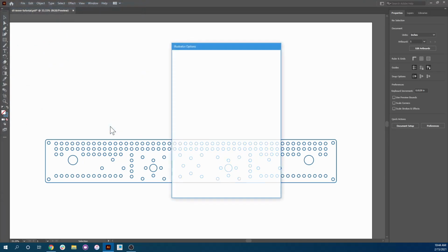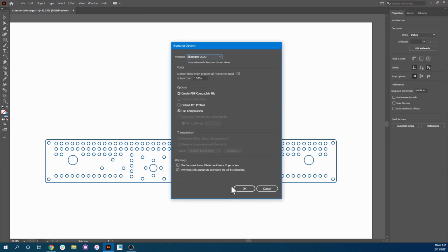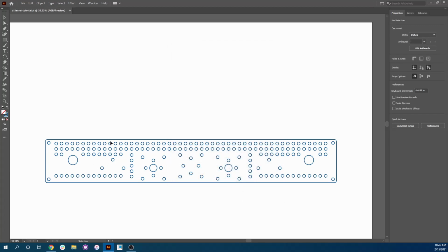If you don't have Illustrator, again, you can use Inkscape. Inkscape's free. We've used it in the past. We just had some issues with it, so I would highly recommend being very careful when you use it, and make sure that you export and import in different file formats than Adobe Illustrator, because Inkscape does not take PDF properly, at least from PTC Creo, and it does not export Adobe Illustrator files. So you have to export in a DXF from Inkscape. So that's just something to keep in mind.